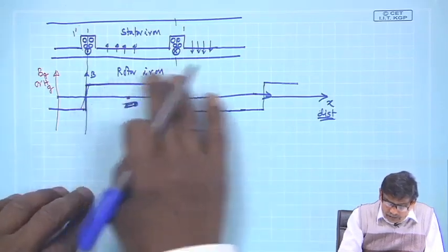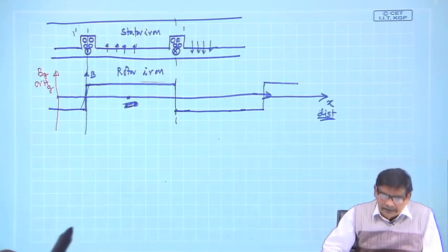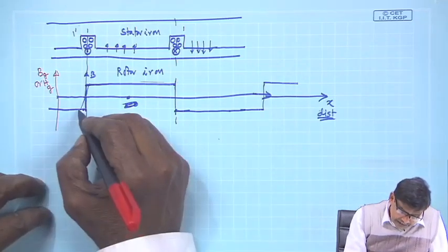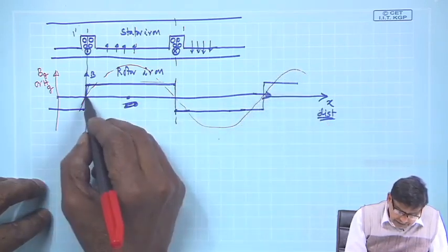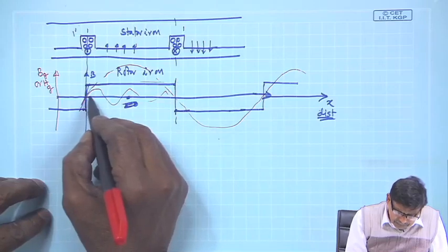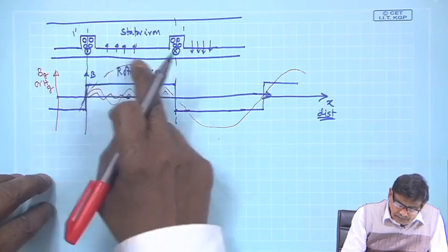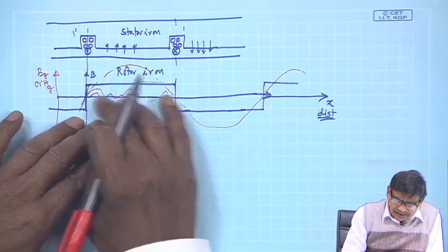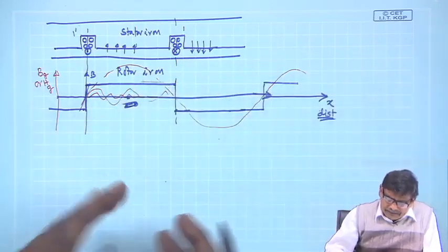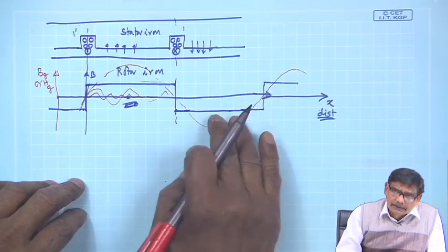For example, if such a square wave voltage is applied to an RL circuit, how to analyze that? I will Fourier analyze, get a fundamental, then third harmonic, then fifth harmonic with reduced amplitude, and for the fundamental if I pretend that okay, these amplitudes are too small compared to these, their effects on current will be less, and you satisfy okay, this is sinusoidal voltage. Of course, in detail it can be analyzed.